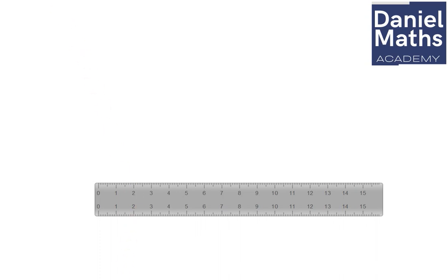All right, so let's draw our center lines. Take note that the line is 100, so I'm going to start from 2. It is a center line: short dash, long one, short dash, long one, short, long, short, long. Don't forget I'm stopping at 12. So I'm going to stop at this point.